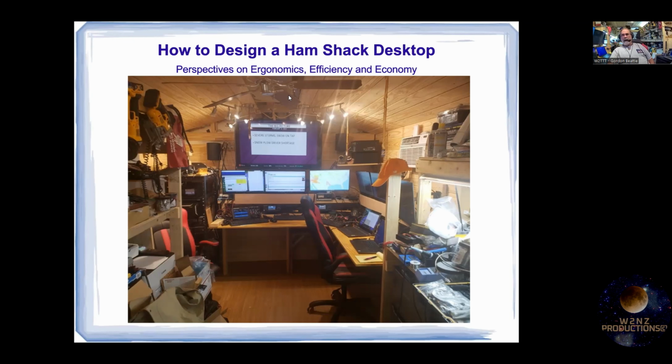And then other ones are going to be extended to go to the first tower, which is not part of this presentation, but it's about 30 feet behind the shack, 35 feet behind the shack. There's a Rohn 45 tower. So part of the grounding comes in off of the power panel right there. And the power panel is directly grounded to that ring right on the wall there.